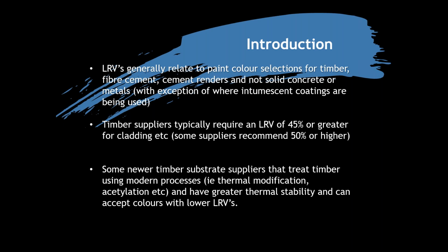Now, one exception there for metals is that where intumescent coatings are used in exterior situations or in exposed interior situations like atriums, typically there is an LRV limit put on the color. Timber suppliers generally require around 45% or greater. Some require 50% or greater now for their cladding